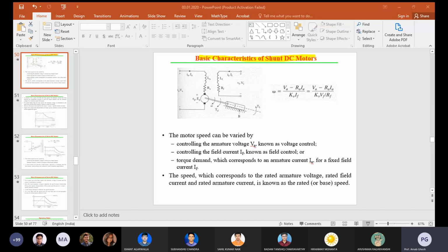A series motor can provide a higher torque, especially for starting. In the case of traction, we have to think about static friction. Initially, in the starting condition, huge torque is required. That can only be given by the series motor, whereas with an induction motor we have to vary the resistance, and if possible we can get it. For this reason, series motors are commonly used for traction applications. This is the basic reason.